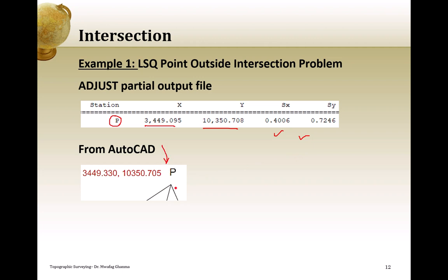I created these examples, and somebody will ask, what does AutoCAD have to do with this? Actually, I created these problems, these examples, using AutoCAD. When you are doing that in AutoCAD, the numbers are perfect. So we add some noise to the measurements, as if we are doing the measurements in the field. Based on that, we will have random errors, and then the solution will be different for every route if you are doing the manual solution of the triangle, while using the least square, we will always have the same solution if we keep the same data collected from the field. So this is the solution.